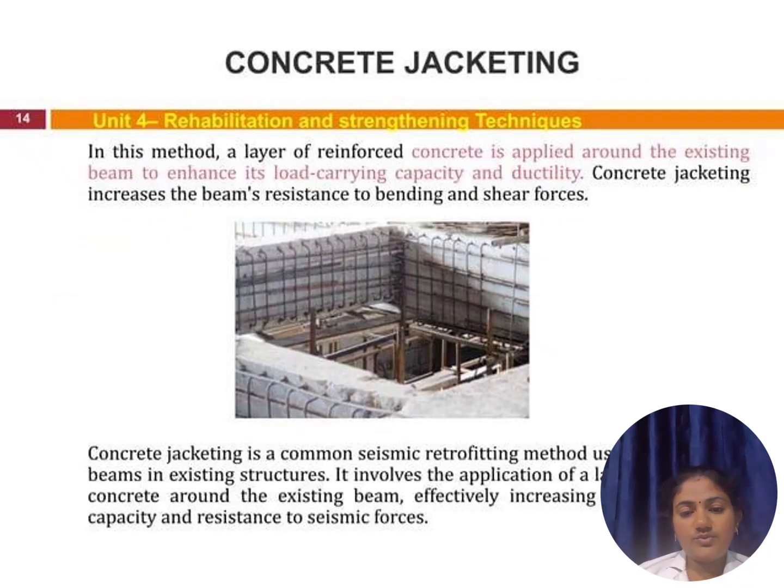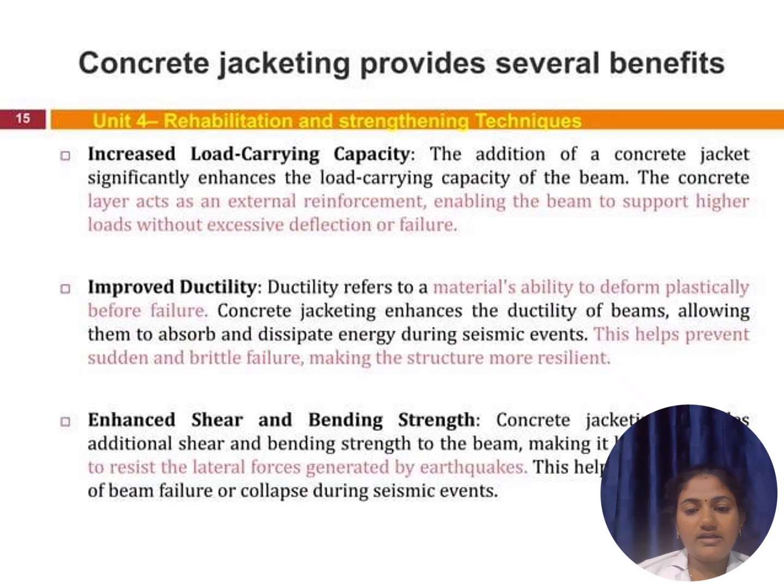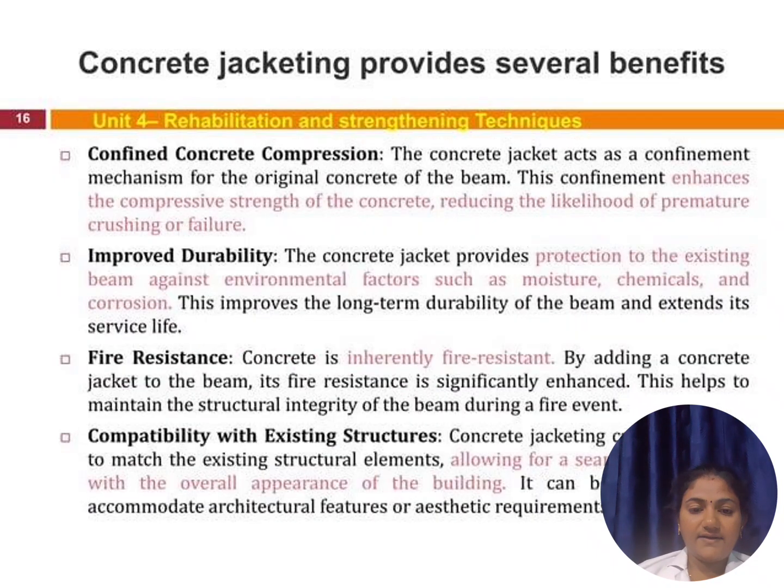And then coming to concrete jacketing, where concrete is applied around the existing beam to enhance its load carrying capacity, and it is a common seismic retrofitting method used for beams of existing structures. Increased load carrying capacity is the main advantage, and it improves the ductility and enhances the bending strength and shear strength. And fire resistance is also better compared to the existing.